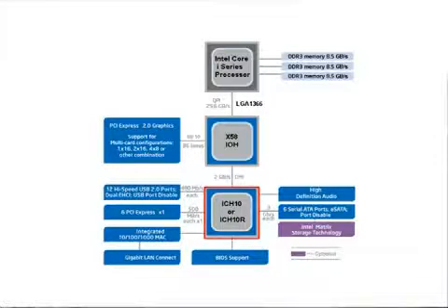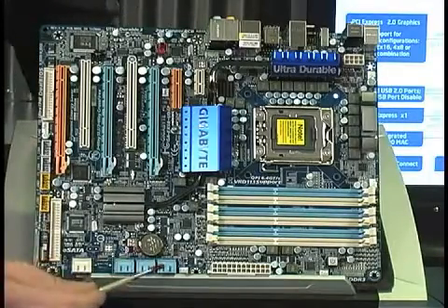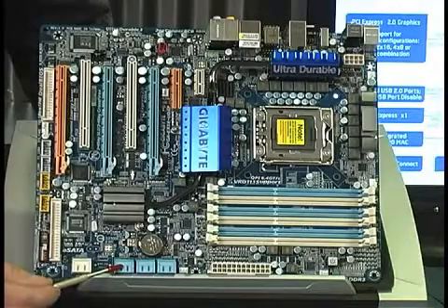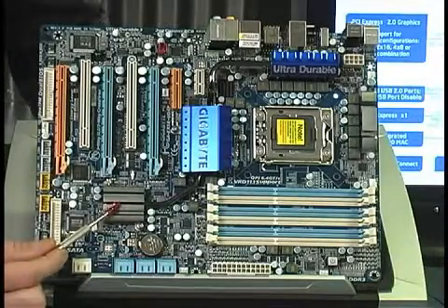What else do we have? Well, a big portion of this is the interface to hard drives, and what we have is 6 serial ATA ports made possible by this particular South Bridge. This one happens to be called the Intel ICH-10R. That's I/O Controller Hub 10R for RAID edition. And we find those ports right here. There are 2, 4, 6 serial ATA ports that are connected to this South Bridge.